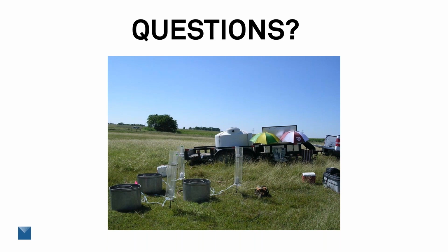So it might be important to understand unsaturated hydraulic conductivity closer to saturation, just to get an idea of how fast that water is going to be moving through the soil, because it's going to be slower than what it would be under saturated hydraulic conductivity. But it also helps you understand how it's going to migrate through the soil and what that wetting front might look like as well.